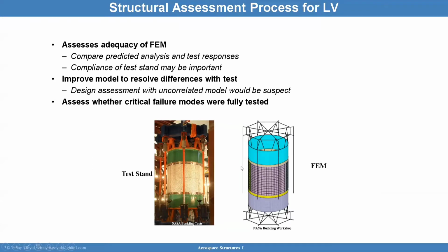So you could have incorrect application of strain gauges compared to drawings. If you put strain gauges near areas of high strain gradients, that can also be a problem, because it will be very hard to get the model right if you have strains near strain gradients.